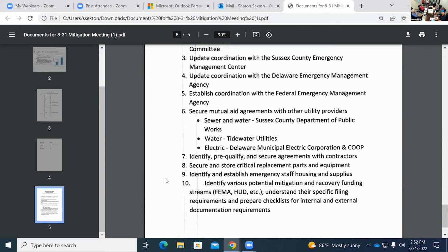We don't have much of a backlog for the treatment plant alone, do we? One of the goals is we're trying to put bypass on the pump stations so that we can utilize bypass capability, coming through with a systematic change out so that more pumps are interchangeable between the pump stations. You've got 27 stations, and you don't want to need a separate pump for each one. And portable emergency generators and things like that from station to station. We don't have that.